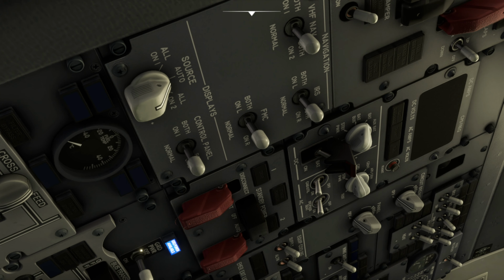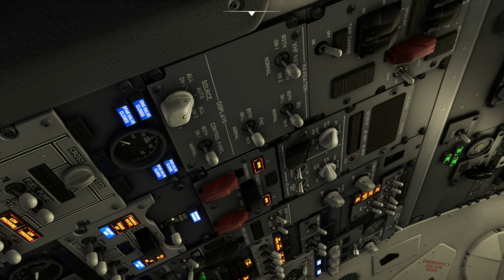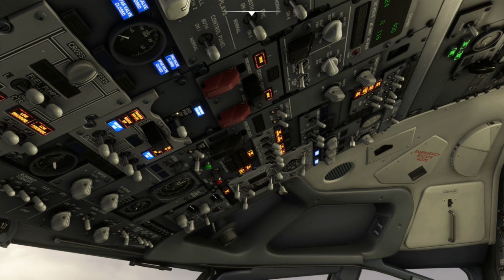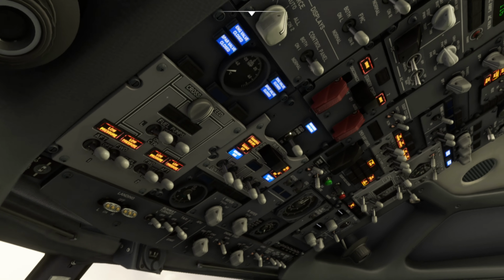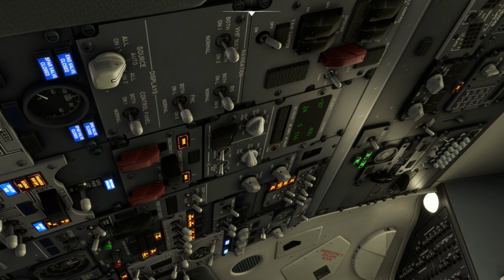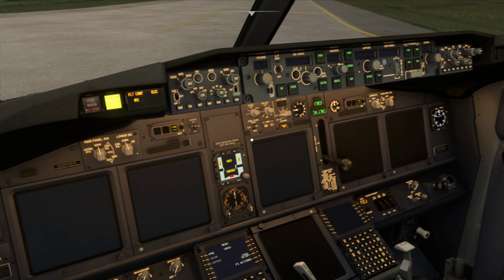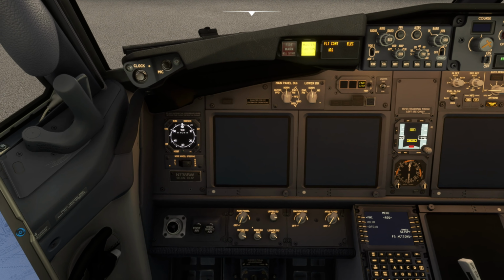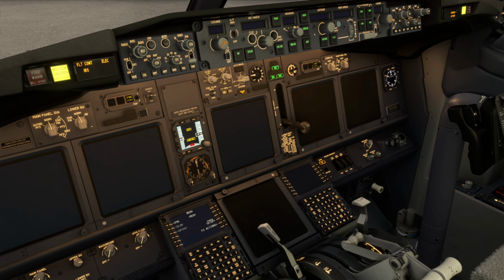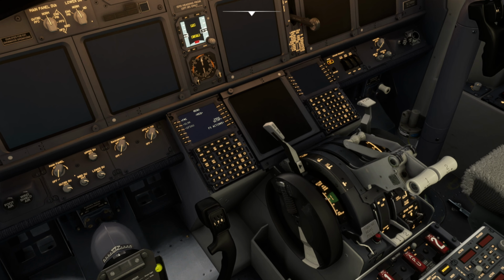However, if we're going to turn this airplane on, we will first turn on battery power on the DC bus. So we turn on DC power, and you see that we have got our overhead panel come on in terms of things that are not operable at the moment because we don't have enough power to operate these systems. You'll see as well our main status board here in terms of things that are running or not running in terms of flight controls and information that we will need to fly the aircraft. So that's all very good.